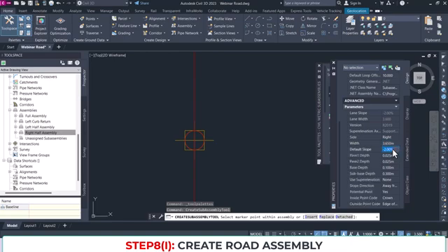Okay, and then my cross slope, now here I'm going to choose 2%. Okay, I'll show you why I do that. I want to not be minus 2%. So let's have all these things as we have it in the previous one. 0.1 here, 0.15 here, and then sub base there, this, and then everything. So let me click on that.